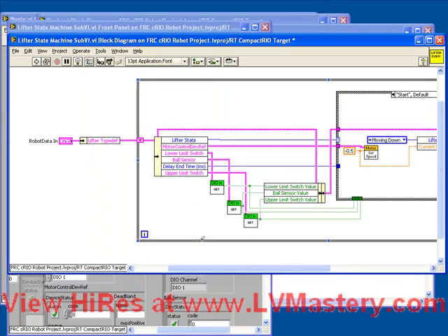But envision a situation where this sub-VI needs to know information about some of the other parameters. Well, the benefit of doing this is that if we wanted to, we could have access to the watchdog device ref, or the joystick device ref, or any of the other parameters which we have placed in the robot data. In this case, all we care about is the lifter, but it's going to make your life easier to always use this robot data and just extract the subtype def that you need.